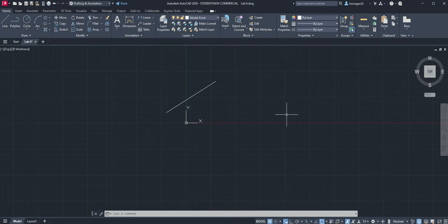I already taught you the absolute and relative. We're doing the absolute coordinate by using the little pound symbol. Every time you use the pound symbol, you know that we're in the absolute coordinate. The formal name for the absolute, even though we commonly say absolute and relative, in mathematics is called the Cartesian coordinate, because it locates an absolute point measured from two perpendicular lines, your x and y.